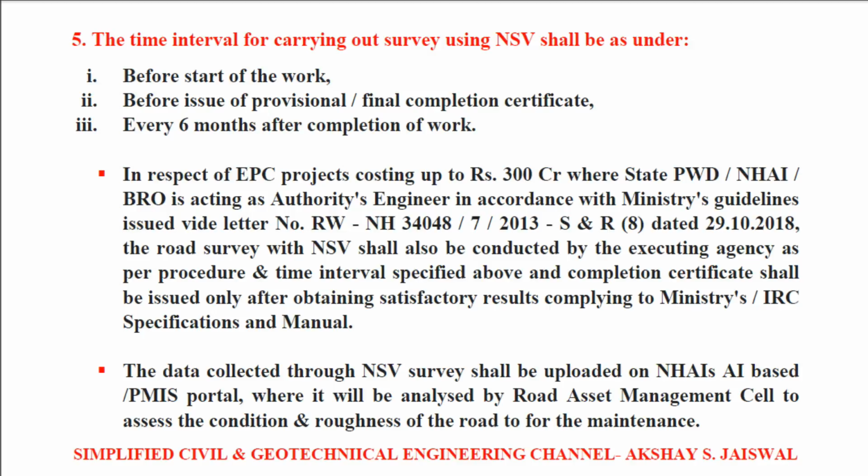The data collected through NSV survey shall be uploaded on NHAI portal, where it will be analyzed by Road Asset Management Cell to assess the condition and roughness of the road for maintenance.